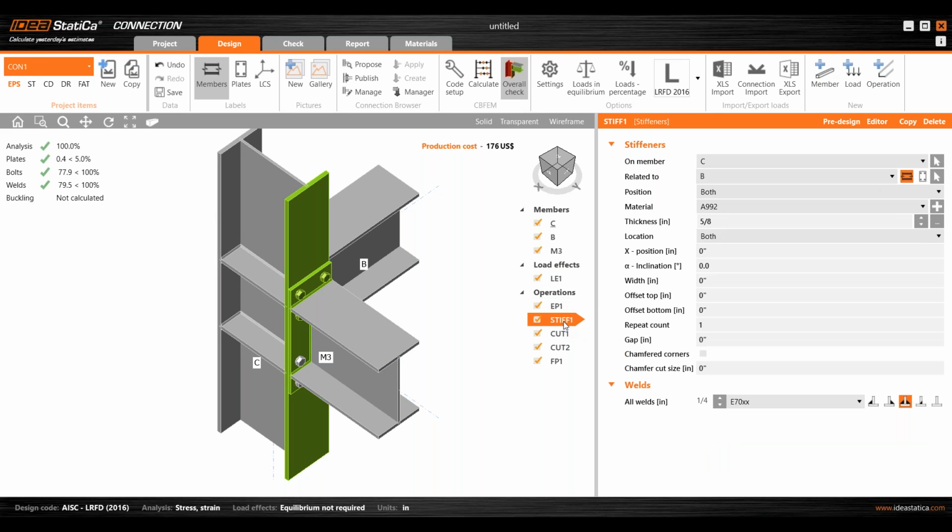So you can go to the stiffener operation and put it just in the front of the connection, and this will work okay. And if you're doing tests with some connections, you can also copy that connection and then do tests in the second one, right, to optimize the design. If not, you can stay with the same first design. Okay, so that's the first example.